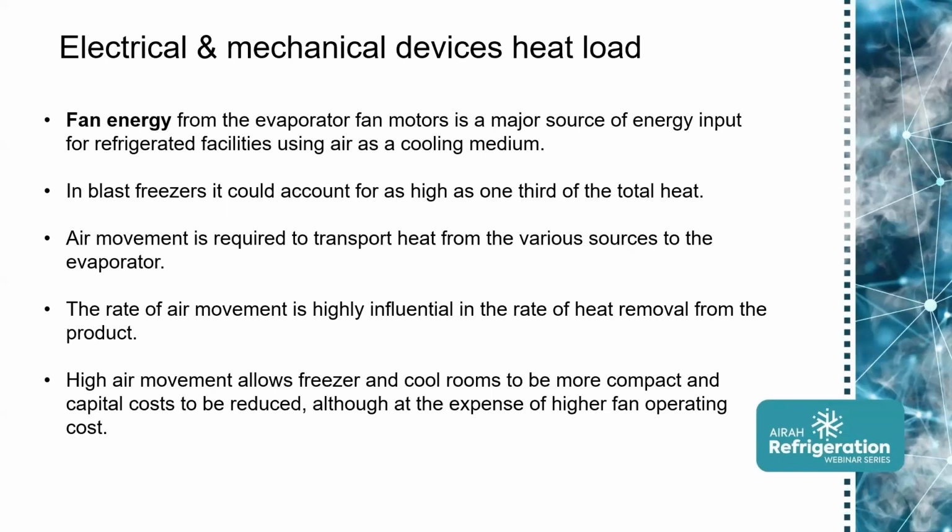And remember, in this case, we need to consider the cost of operating the fans. There's the operating cost, plus you have the heat load due to these fan motors, which increases the size of the refrigeration plant, meaning you also will increase the running cost of the refrigeration plant as well. Hence, we're paying for it twice. And that could explain why with snap freezing a product, to save energy, you go from blast freezing to plate freezing, where you eliminate that source of heat into the room.